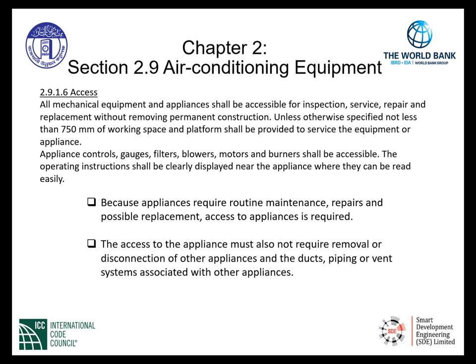Now, because appliances require routine maintenance, repairs, and possible replacement, access to appliances is required. We need to be able to provide plenty of space for service personnel and repairs to be made on permanently installed appliances. Therefore, the access to the appliance must not also require removal or disconnection of any other appliances, ducts, piping, or vent systems associated with other appliances.